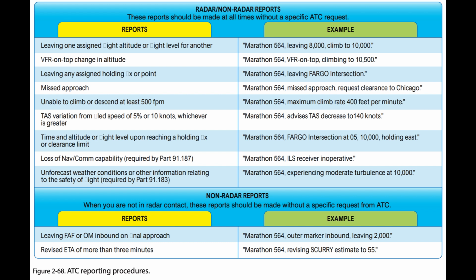Subsequent to being advised that the controller has established radar contact, this fact is not repeated to the pilot when handed off to another controller. At times, the aircraft identity is confirmed by the receiving controller. However, this should not be construed to mean that radar contact has been lost. The identity of transponder-equipped aircraft is confirmed by asking the pilot to ident, squawk standby, or to change codes. Aircraft without transponders are advised of their position to confirm identity. In this case, the pilot is expected to advise the controller if in disagreement with the position given.